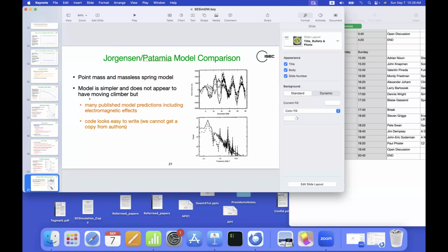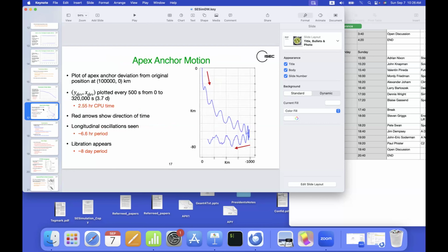And it's going to continue doing that unless you find a way to damp out the libration mode. You didn't do the full trip to GEO, did you? So you didn't see the recovery backwards and then the swing to the left. We really need to see the whole picture. Yes, it swings that far, but it's way out there and you can plan for it. You can use the apex anchor unreel and reel in to compensate for it in real time so you can straighten that out. There are a lot of ways to do it.